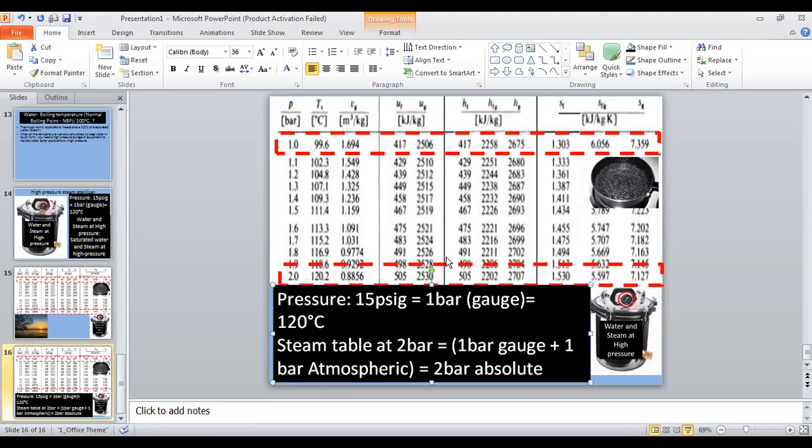But generally, don't get mistaken, gauge pressure is gauge pressure and it shows 0 at atmospheric. It's the real pressure inside; plus the ambient atmospheric pressure, you have the absolute, as in the table. So this is today's discussion.